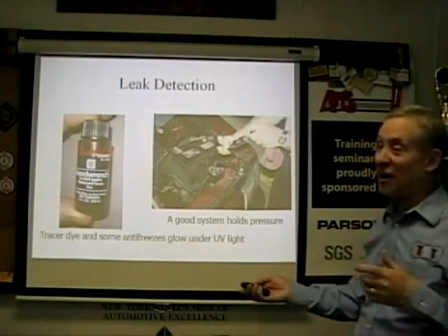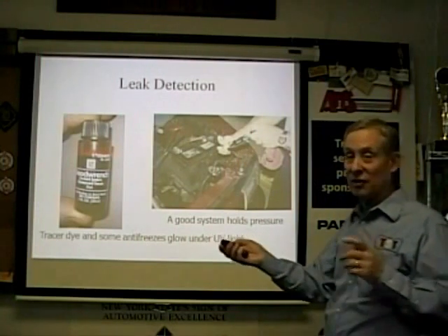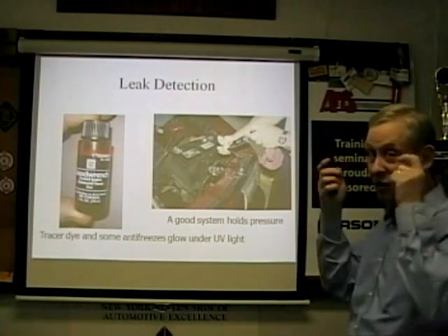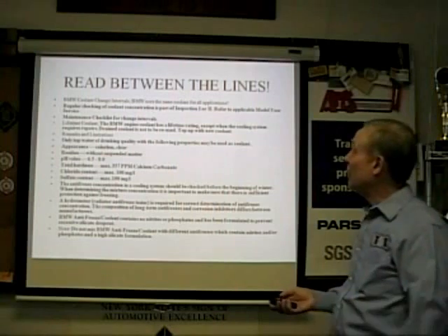Make sure that the goggles you're wearing are the same frequency so you can actually see it, because different brands use different frequencies. Different frequency black lights, different frequency, different color yellow or orange goggles. They use different stuff. Read between the lines.